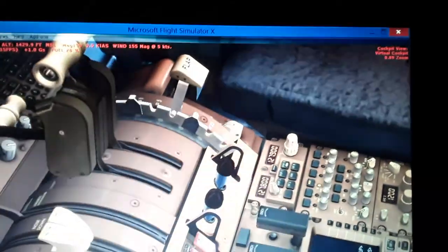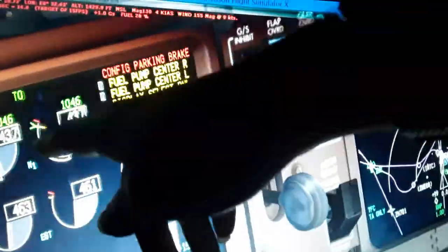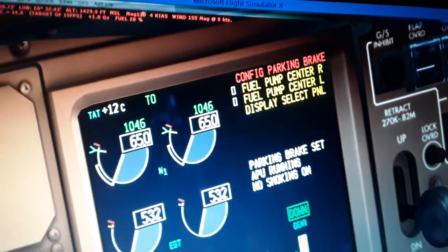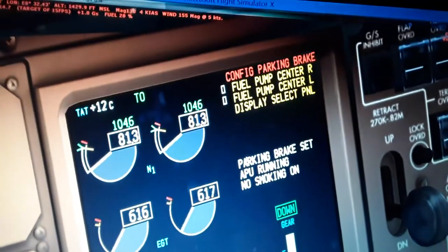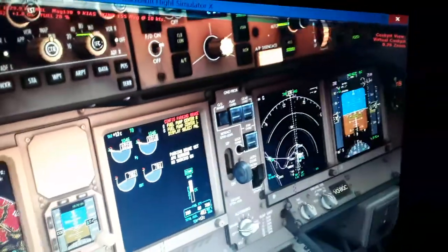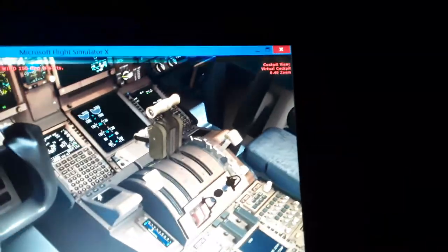We move the thrust levers forward to balance the thrust over here, the takeoff thrust. The N1 is increasing. You can see the thrust lever limit here for takeoff has to be about this green needle, about 103%. So we disarm the parking brakes and go.